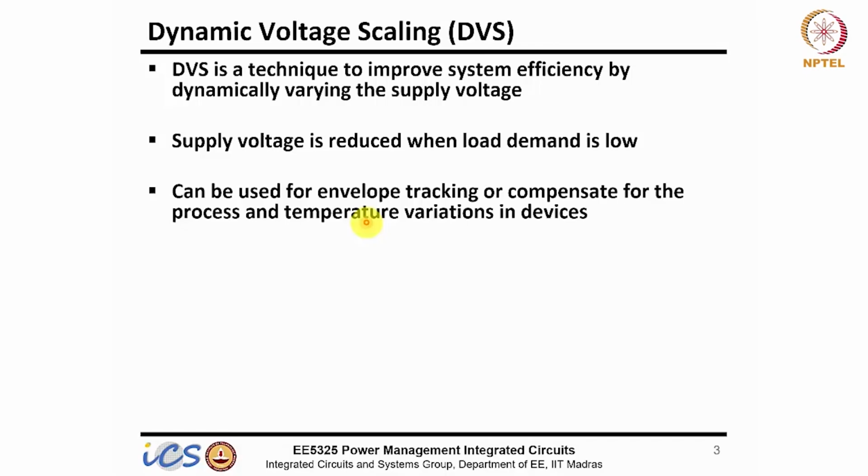And so what you do in dynamic voltage scaling is design at a typical corner, and if you have some way to track the PVT, and I think we talked about this, you can have a ring oscillator. So let's say you are able to track the process and temperature, that will give you the code.